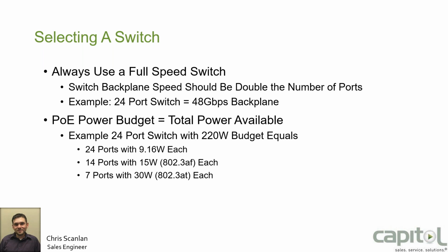Look at this example right here for a 24-port switch with a 220 watt budget. You think 220 watts, that's a lot of power. Well, let's start looking at this. If those devices are only going to take 9 watts or 9.16 watts, you can use all 24 ports. If it's using standard PoE, that's actually going to be a 15 watt rating, you can only use up to 14 of those ports. And if it's PoE Plus devices, cameras with heaters, high-powered access points, and other devices, you're only going to be able to power 7 devices off of a 24-port switch.